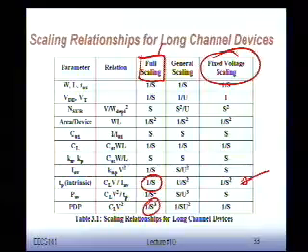That's really cool. However, look at the power dissipation. The energy per gate, instead of scaling down as S to the third, actually goes up as 1 over S. You put more and more gates on the same chip, you see your power going up and up and up, and you run into barriers. That's why we went to this general scaling, where you put this as a function of S and U. Okay? But all of those things can be easily derived.